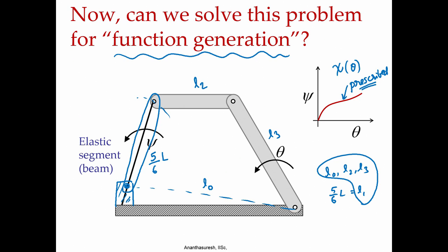and we know that even if it were a cantilever beam, it would only move along a circular arc, very close, an approximation, but very close approximation. Okay. And when a linkage is like this, the load at this point can come in any direction. It is a pin joint, there will not be any movement as yet, but the force can come in any which way, right. And that is why we had considered on the cantilever beam loads both transverse and axial, so that the inclined load in a lot of different directions.